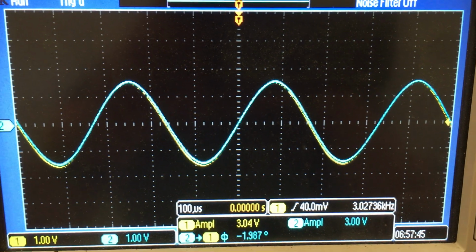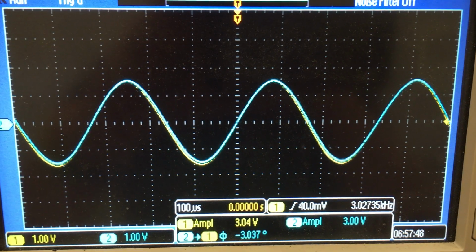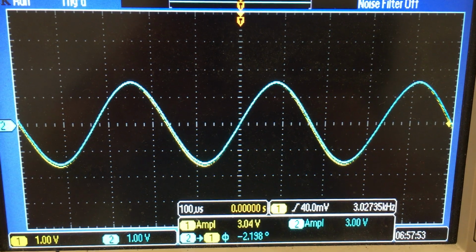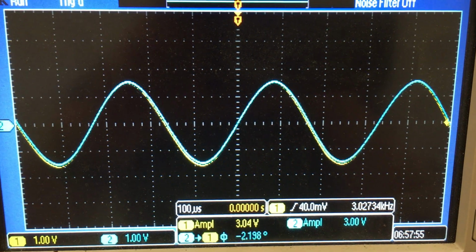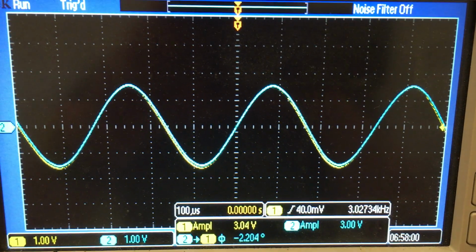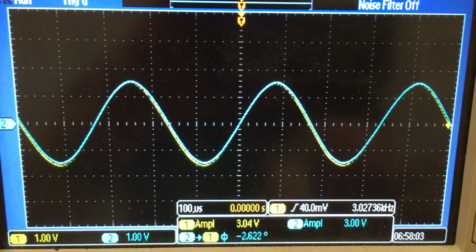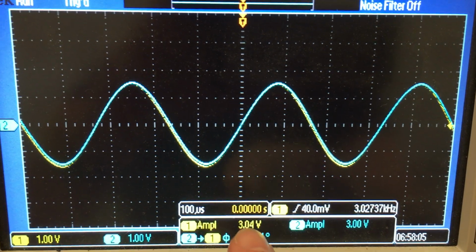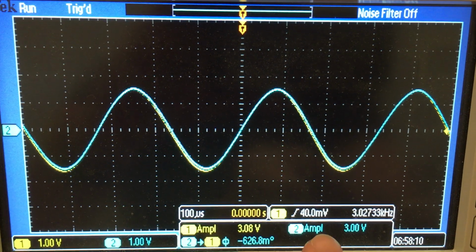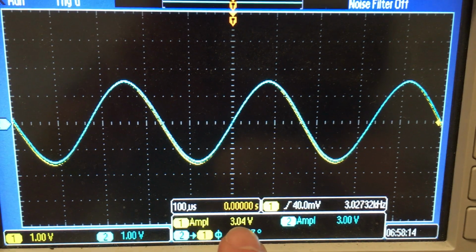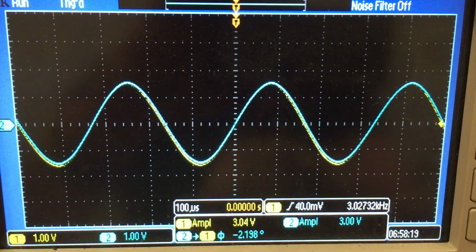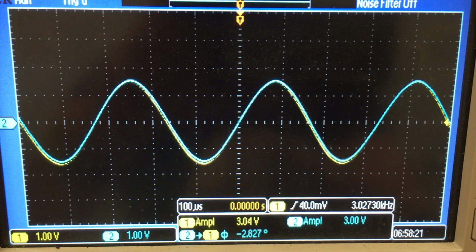And as we go down in frequency, the reactance or apparent resistance of the capacitor goes up, giving us a larger shift between the current in the circuit and the voltage applied to the circuit from the AC source. And also the resistor here is dropping all the volts at high frequencies, but at low frequencies the resistor only drops a portion of the volts applied to the circuit, suggesting that the capacitor's apparent resistance, so reactance, is relatively high at low frequencies.